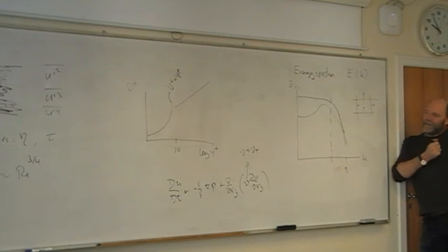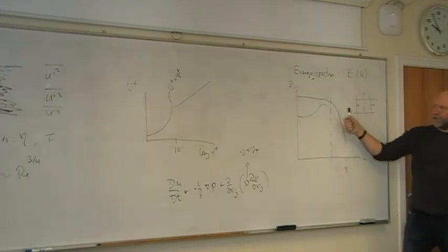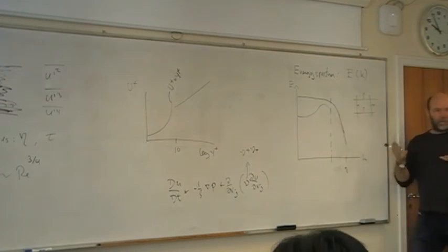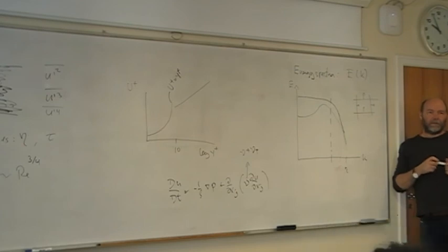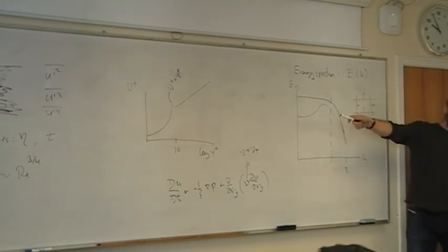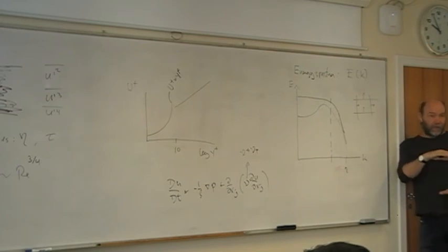Yeah, of course, if you are pushing your cells bigger and bigger here and have a large amount of this energy spectra sort of skipped, of course you're going to have a bad answer, a bad simulation. Then maybe our answer will be much better. Especially when you have a geometry like this. It's a one-dimensional problem for crying out loud, so you can have it very accurately with one dimension.